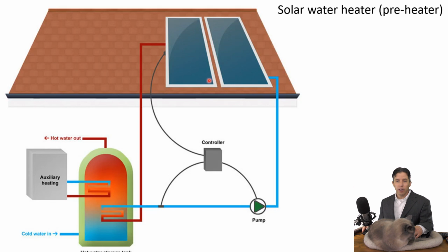What a preheater for your water heater does is the cold water coming from the ground moves through these boxes, and in these boxes are just some pipes that are sitting in the sun, and it preheats the water before it goes into the water heater. If the groundwater is, say, 40 degrees, then normally without this system, you'd have 40-degree water going into your water heater and having to warm that up from 40 to 140, let's say.